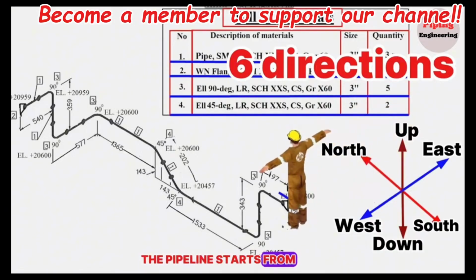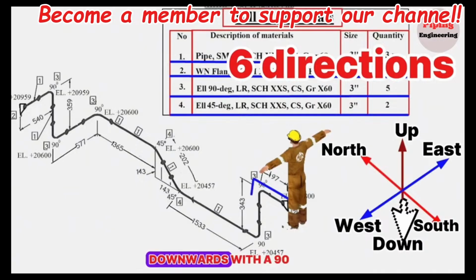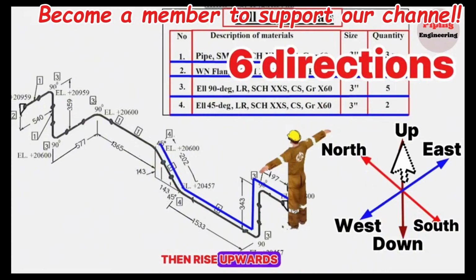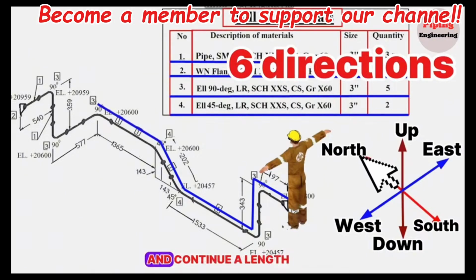The pipeline starts from this flange and extends northwards a length of 197 millimeters. At this point, the pipeline turns downwards with a 90-degree elbow and continues a length of 343 millimeters. Then the pipeline turns northwards with a 90-degree elbow and continues a length of 1,533 millimeters. At this point, the pipeline first continues northwards a length of 143 millimeters, then rises upwards 143 millimeters at a 45-degree elbow angle. Then the pipeline extends northwards with a 45-degree elbow and continues a length of 1,365 millimeters.